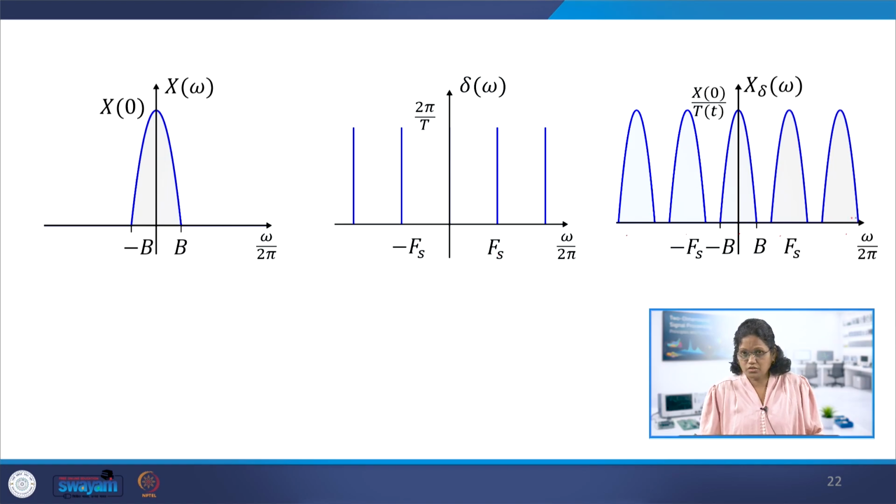So this is the discretization process. When you discretize a signal in the time domain, in the frequency domain the baseband spectrum of this particular signal gets repeated. So the discrete signal will have a repetition, a periodic spectrum. This is centered at Fs, this is at 0, this is centered at 2 Fs, this is minus Fs, and here is minus 2 Fs. So the discretized or sampled signal will have a spectrum like that.